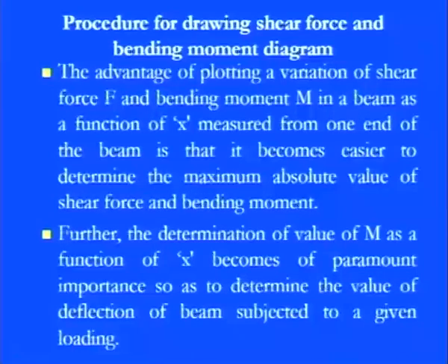Further, the determination of the value of M as a function of x becomes of paramount importance so as to determine the value of deflection of a beam subjected to a given loading, which is very, very important, because if somebody wants to design the beam, he should know where the maximum deflection is and where the minimum deflection is, so that we can put in a factor of safety against that kind of loading, so that whatever the displacement or deflection is, it can be minimized,